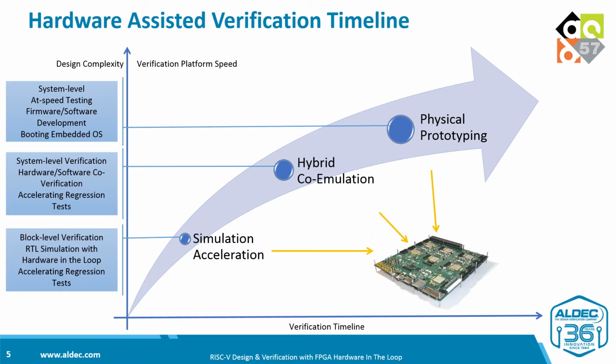So who will benefit from hybrid co-emulation? The hardware verification team receives a very fast model for running system-level regression tests. Any system integration bugs can be traced conveniently in the simulation-like environment because the same test benches are used during co-emulation. Now the software team receives a complete and accurate system-on-chip model to run their software and firmware components without compromising any functionality.